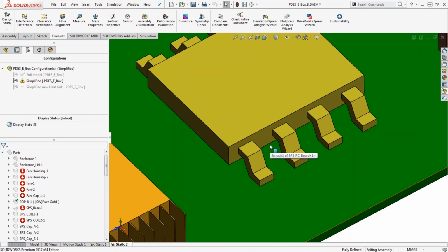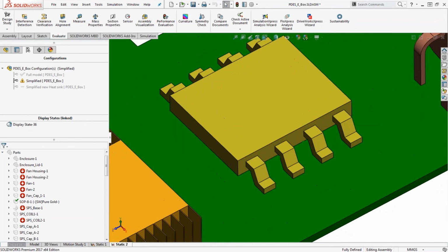Be careful with that because you are affecting the overall features of the part, but you're at least getting rid of that issue. So that being said, how can we do that? We can do that by utilizing the cavity feature tool that's available within your parts, within your single components. It's easier to do it in context of the assembly. So if this is the component that I want to remove material from, this is going to be the part that I actually edit.